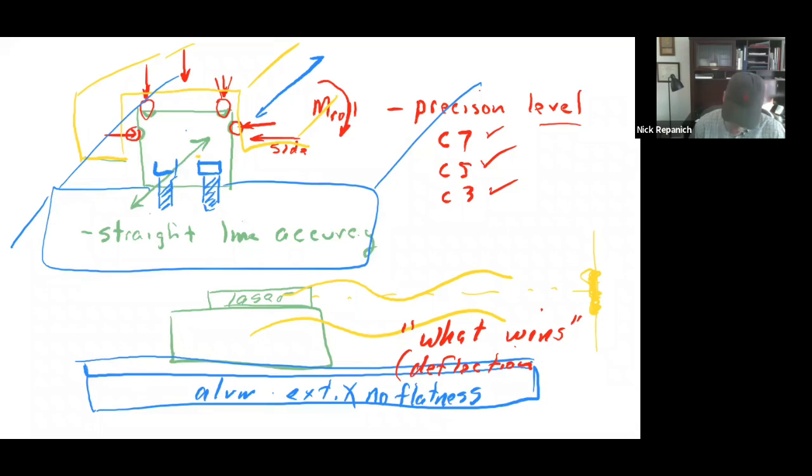Instead, you go buy a machined surface if you want true flatness, or you go out and get a piece of metal and machine it as best as you're willing to pay on a CNC to have a machined surface, and you mount it to the machined surface.